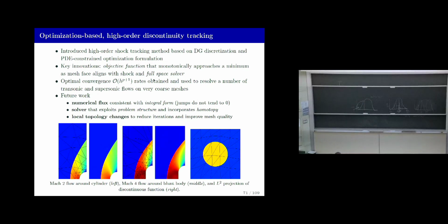You'd have to do all sorts of mesh operations once your shock gets too far and you have to start flipping elements. So that wouldn't be ideal. What I'm actually more optimistic about is you could take a space-time approach for this. You think about your domain as both space and time, and you mesh that. Now your shock is just a discontinuity in space-time, even a moving one. And you don't have to do the whole domain at once. You could do slabs, and it would be a reasonable approach. And because we operate on meshes that are orders of magnitude coarser than the counterparts you would need if you're doing limiting or artificial viscosity or whatever, I don't really see it as a big issue. It's something I'm working on right now.